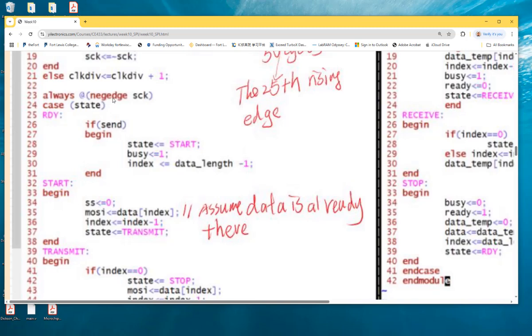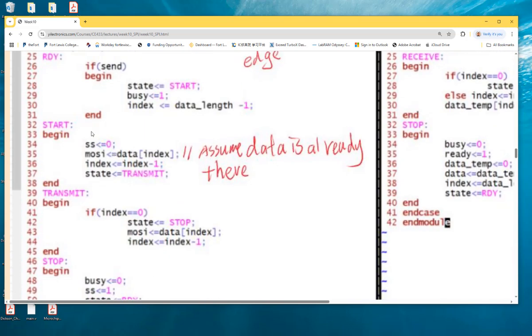Okay, keep in mind. When the next one arrives, it detects the start state, directly enters this state, right? And you can see this is put down to 0, and directly places that data in this vector onto the line. That simple. Okay? When it's allowed to send the data, it directly places the data to the MOSI line. That's it.